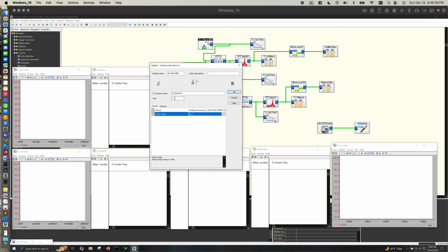If I had a current viewing resistor and the proper circuitry set up, I could change this to amperage. And then because there's 2 scope options, even though it defaults to scope channel 1, I could also enable channel 2, which is 0 indexed here. So 0 is scope channel 1, 1 is scope channel 2. So you just add that by hitting this little plus button over here, and whichever one you're currently configuring is the one in green. So that kind of throws me off. The red one is the one I'm not currently configuring here. But the green one is the one that you're currently configuring.